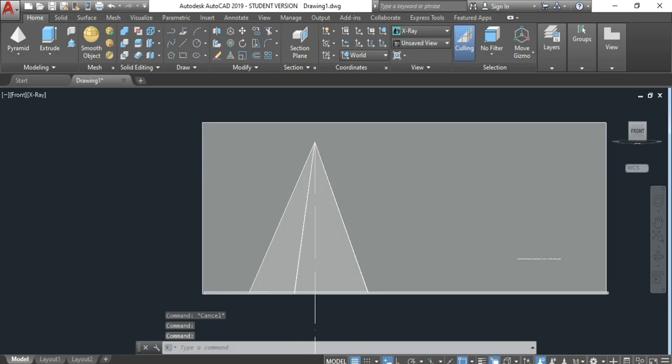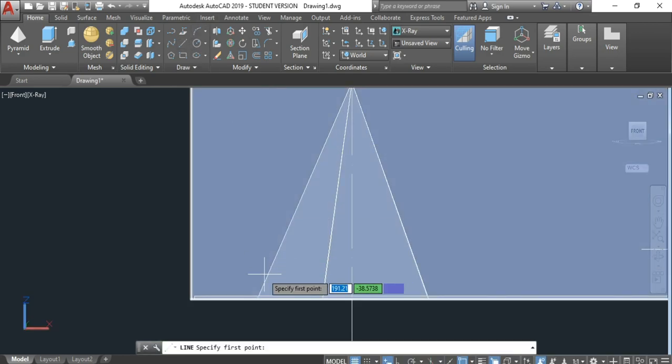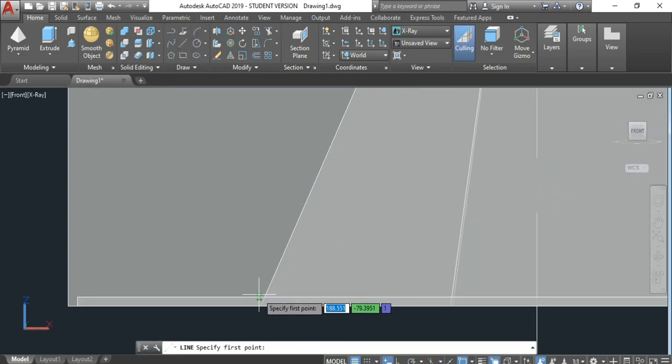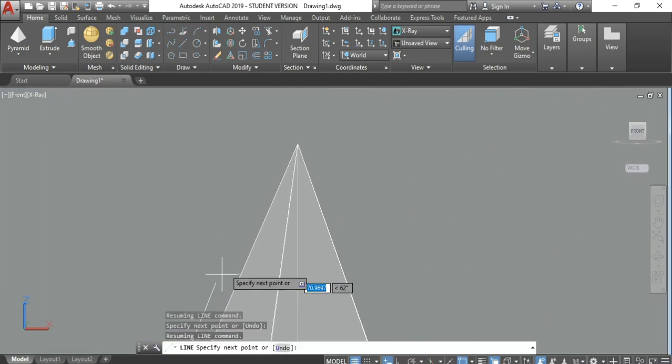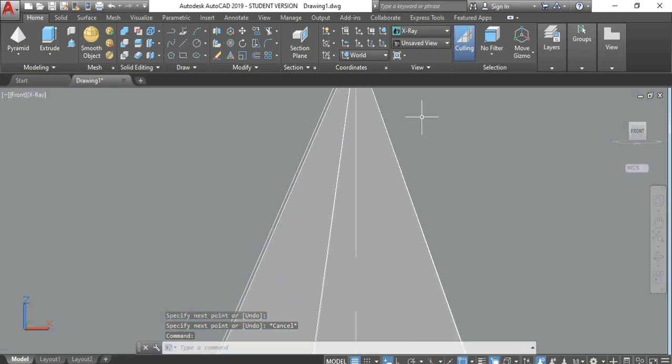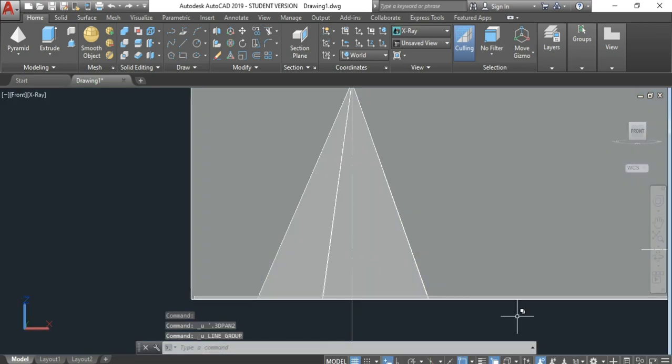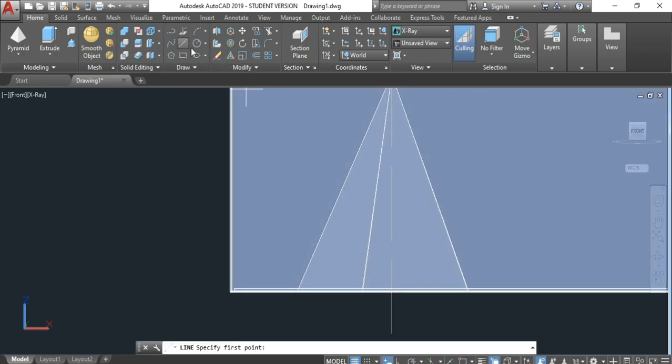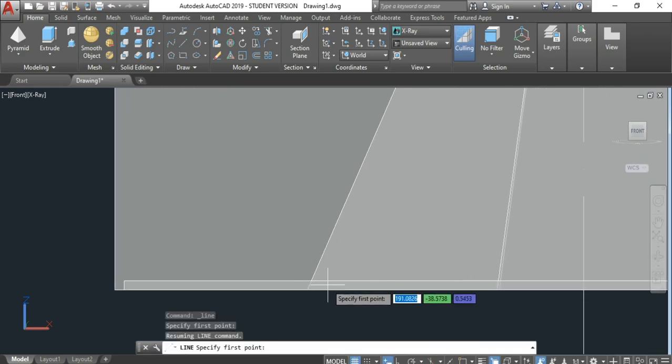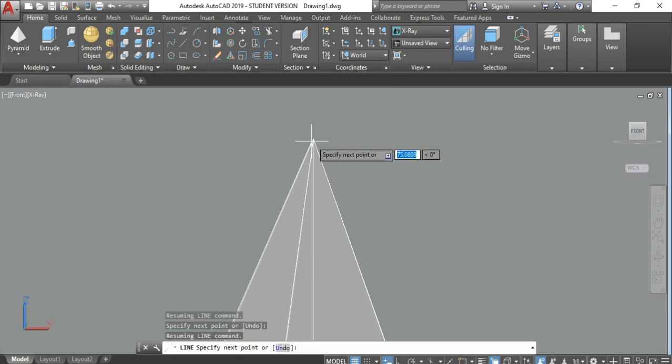If you're getting that green tick, it means whatever geometry you want to create is being created in that layer. Okay, if I turn off the object snap, I think I will be able to create them. Yeah, I've turned off the object snap, so that's why you guys need to learn about this object snap. If the object snap is turned off,